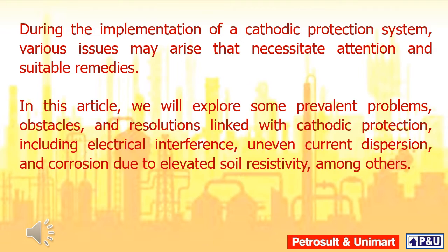During the implementation of a cathodic protection system, various issues may arise that necessitate attention and suitable remedies. In this article, we will explore some prevalent problems, obstacles, and resolutions linked with cathodic protection, including electrical interference, uneven current dispersion, and corrosion due to elevated soil resistivity, among others.